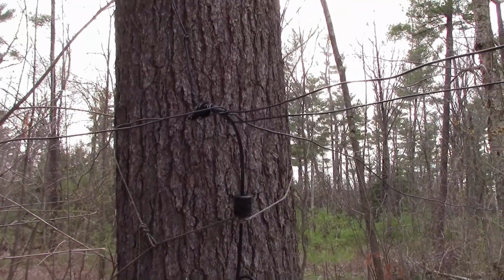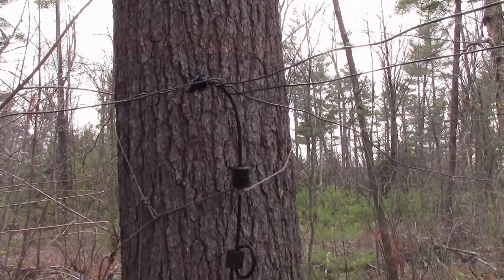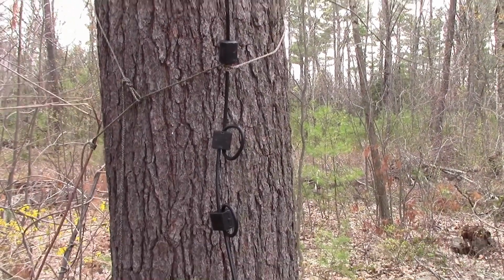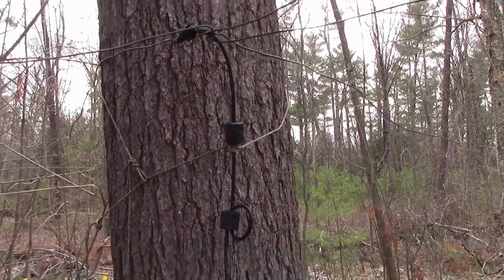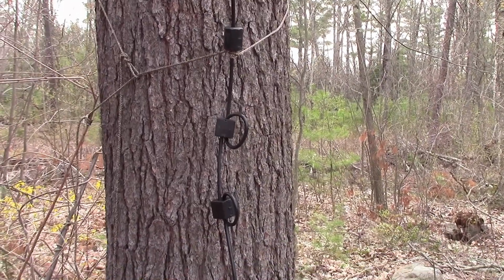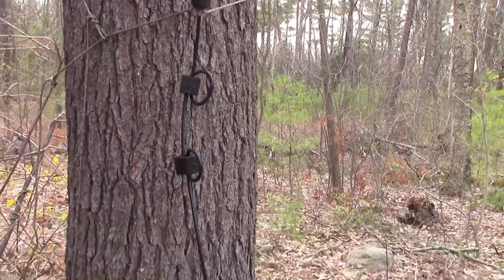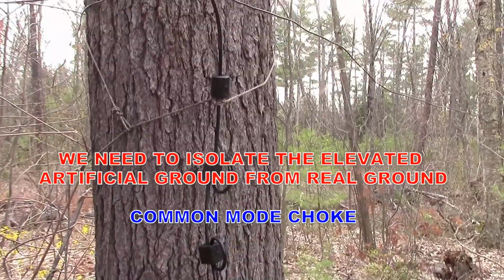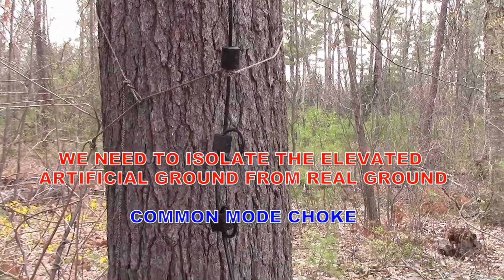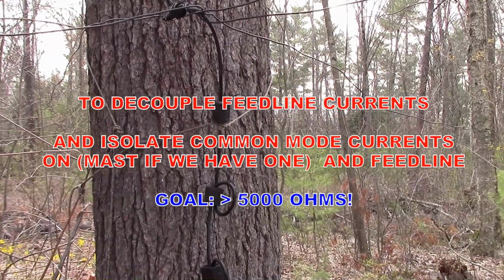Okay, here we are, the finished product. We've got 5 radials. They're coming out at pretty equal angles. And I've got 3 ferrite beads. One just clicked on, and I've got 2 with a loop through. Why are we doing this? We want to decouple the coax, which is grounded. As a matter of fact, the coax is buried. We do not want that to become part of our radial system because that's part of the ground losses. So we want to isolate ourselves from ground and allow the radials to become the artificial ground plane.